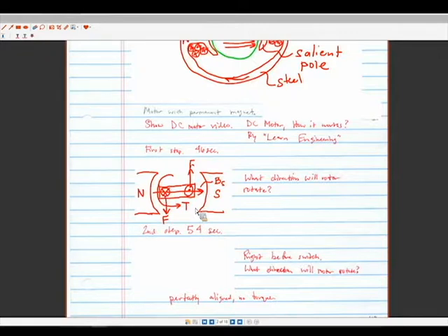So now if we start to look at moment arms, we're going to see that the torque is going to start to disappear. Going back and just illustrating this, same idea, the stator doesn't change in a DC motor. So everything with the stator stays consistent. All right, but my rotor has rotated 90 degrees. And for this point in time, our current is going in exactly the same direction.